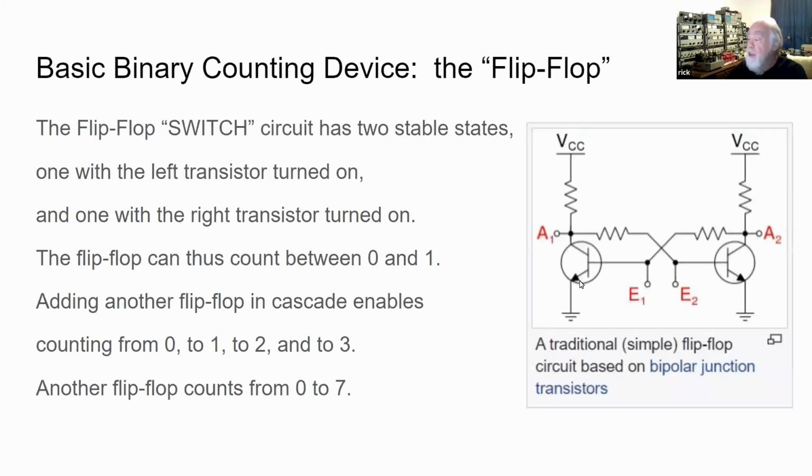Now, we can use transistors as the basic building block for a computer. To do that, we could connect two transistors back to back. I know this is probably getting into more detail than everybody can comprehend with such a short introduction. But basically, one transistor conducts with a positive input, causing the output to go negative. And this negative is applied to this transistor to turn it off.